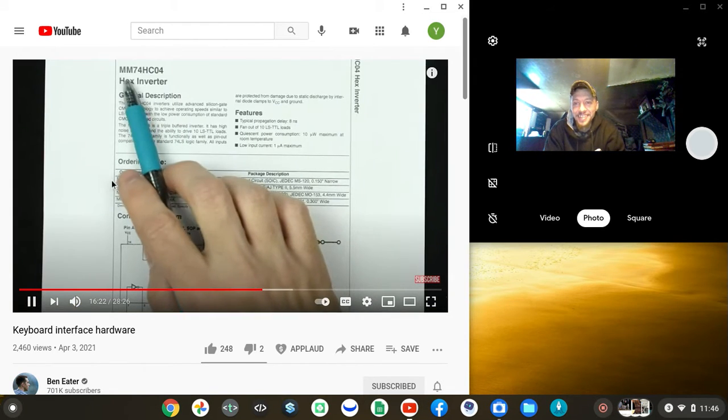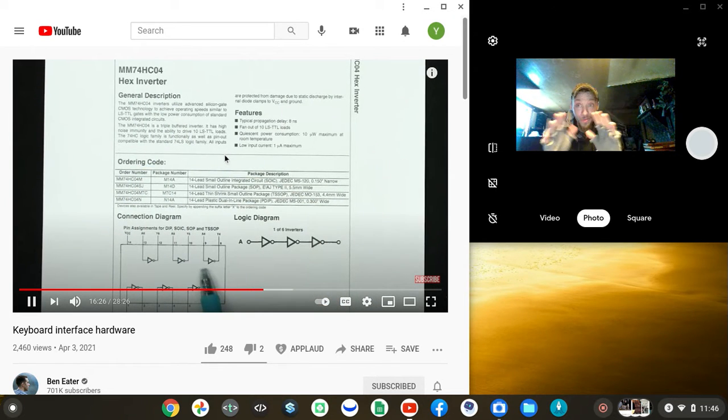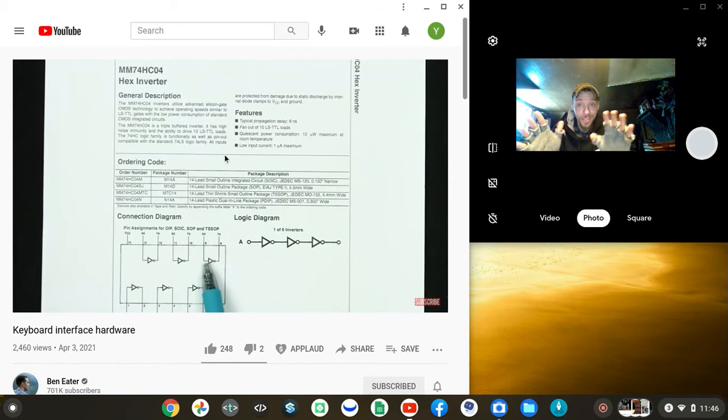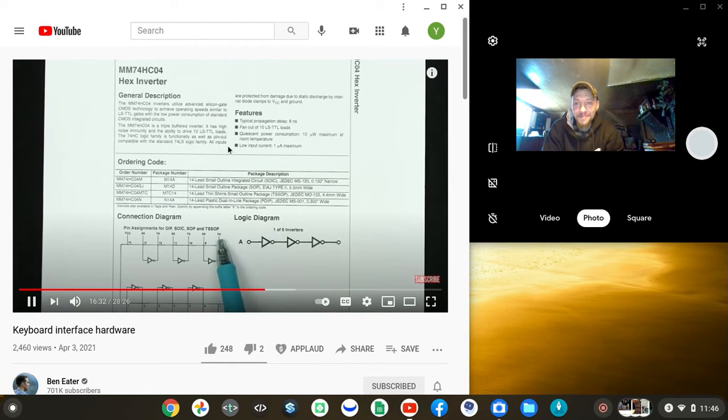And actually, if we look at the data sheet for the 74HC04, which is that inverter we're using, there's a bunch of them all doing it at the same time. We're feeding that decaying signal into one of these inverters, and we're getting that noise on that output. And then we're feeding that noise in as the interrupt to our CPU, and we're detecting extra rising edges there.